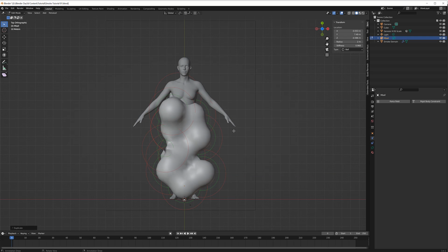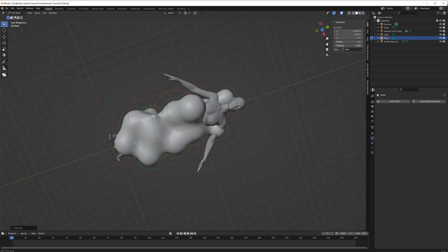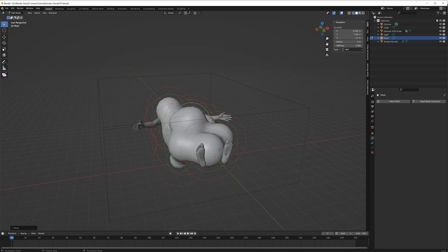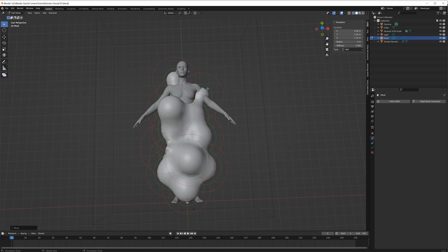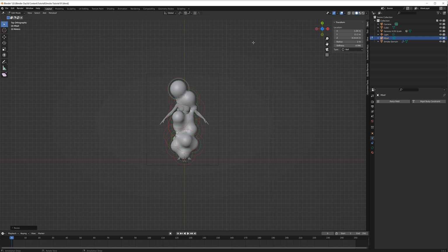And metaballs are about the best tool you can use for creating a globby, irregular object. And the other thing is that this is non-destructive, so you can continue moving any metaball that you've already moved, even though it appears merged with all of the others. So I'm going to create this metaball smoke column.